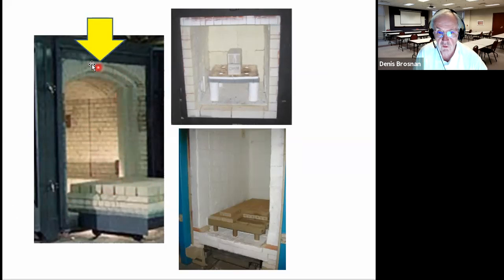And you can see in this kiln, there's a typical arch shape, which you will find in the roof of many kilns. Modern kilns sometimes have flat suspended roofs where the refractory bricks are hung from above the kiln to constitute a flat lining. So these are typical bricks in this kiln.